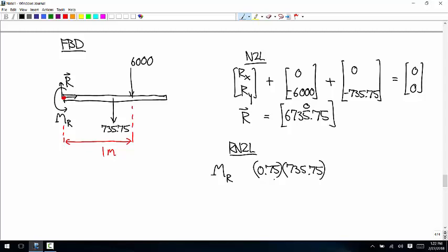And now we'll think about the direction of the rotation that produces. So if the thing rotated freely around this point, you apply a force like that, would it rotate clockwise or counterclockwise? Clockwise, so this is negative. And then the moment arm for the 6,000 is 1. I'll do the sign in a second. Force is 6,000.